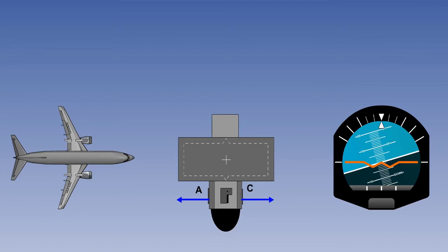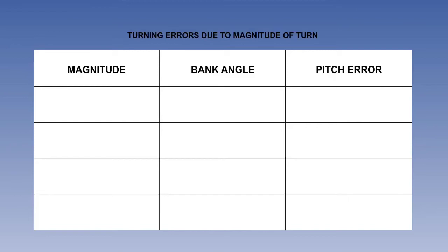The magnitude of the errors in both pitch and roll will be complex and will vary with the speed and the rate of turn. For a chosen speed and rate of turn, it is possible to compensate for these errors by tilting the top of the rotor axis slightly forward and slightly to the left. However, if we consider an uncorrected classic gyro, that is, an air-driven gyro rotating anticlockwise when viewed from above, the following errors will occur.